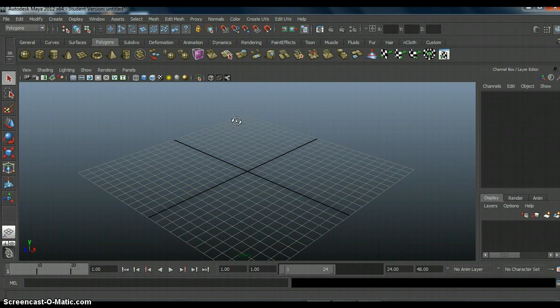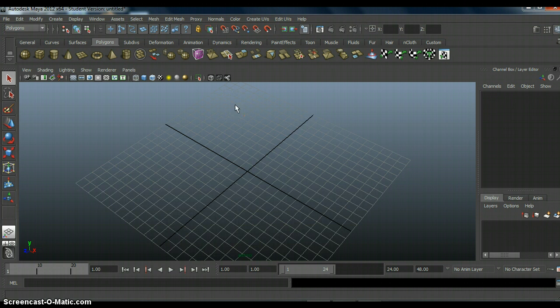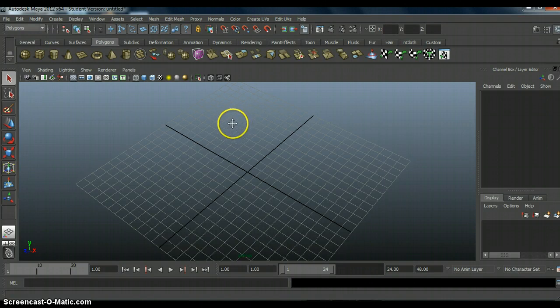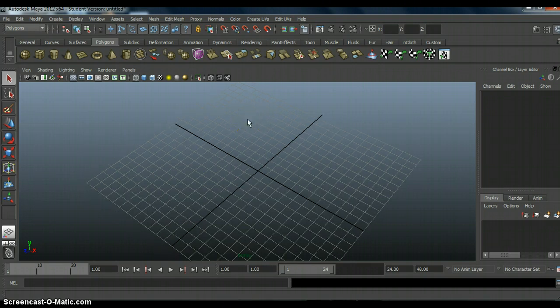You can rotate up, down, left, and right, and of course it will move around an object as you rotate, as opposed to just sliding, as can be done in the pan view, which you can activate by hitting the Alt button on the keyboard and the middle button on your mouse. So this allows you to slide up, down, left, and right on a two-dimensional plane, and unlike Orbit, it stays on this two-dimensional plane, and it won't move around your object in the three-dimensional space.